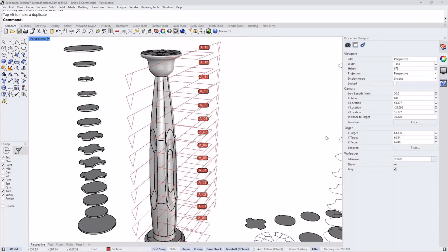Yeah, you can think of extracting a clipping section in place. This is in its natural 3D place. It basically intersects the clipping plane with the objects or the model and creates it there in the 3D space. If you want to extract it as a drawing, with backgrounds, maybe to put in layouts, or that is flat on the XY plane, then you run the clipping drawings command. So this is the main distinction between the two.